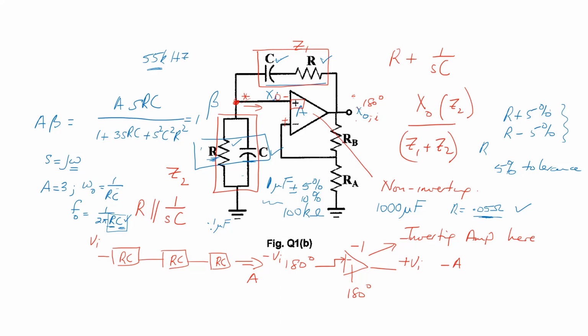But I wouldn't penalize too much if you were to say, okay, use C as 10 microfarads and you get a value of, let's say, 100 ohms. It won't be 100 ohms, but something kind of small. From the time you pick a value and start to get resistances less than 100 ohms, then choose a smaller capacitor. So just choose a capacitor and build the circuit for the frequency around it.